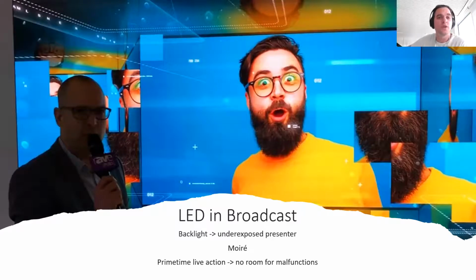The other option would be to dim the wall. And here's the problem. Not all LED walls perform as well when dimmed. It can introduce a lot of different side effects like flickering or decolorization or loss of bit depth. And it's about loss of bit depth that I am going to try to explain. It's the first time that I'm actually going to try to explain it, for people who I suppose not everybody will be that familiar with it.